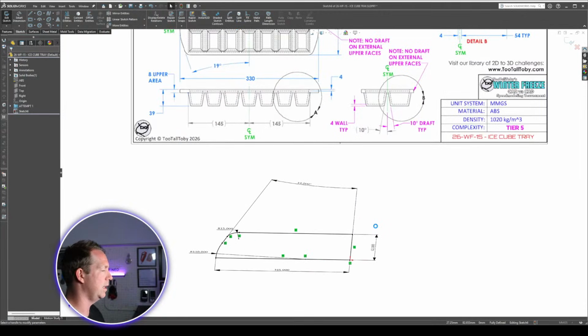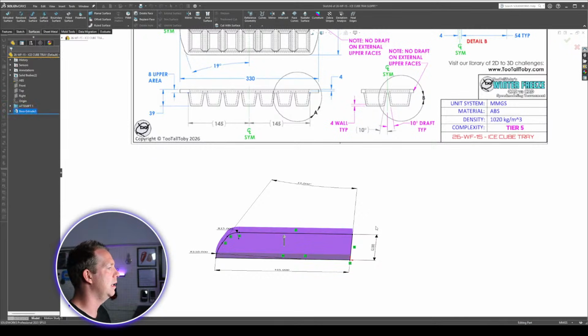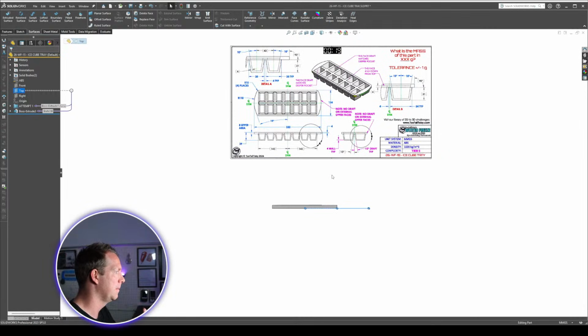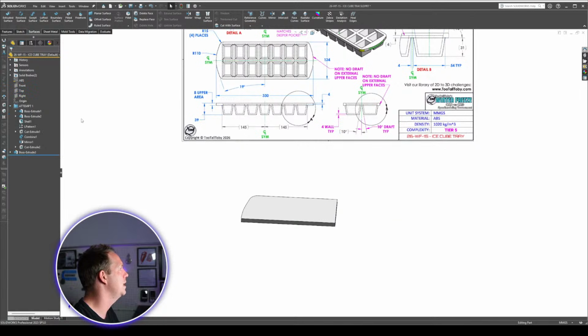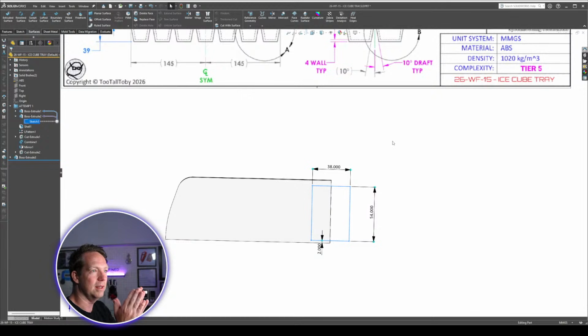Now I think it's useful here to extrude up. I'm going to get 8, because then you can still use the top plane, which is here, to do the parts that are going down underneath. Now this is where, in my first attempt, I probably took longer than needed, because I was trying to work out the exact position to get one in the middle.